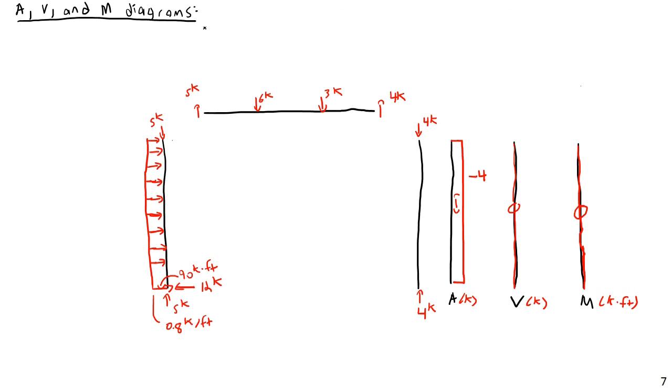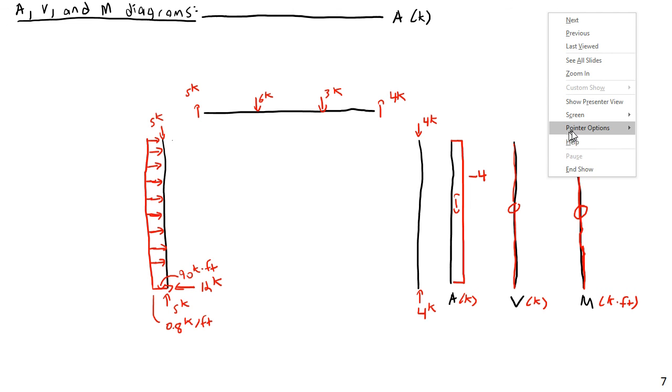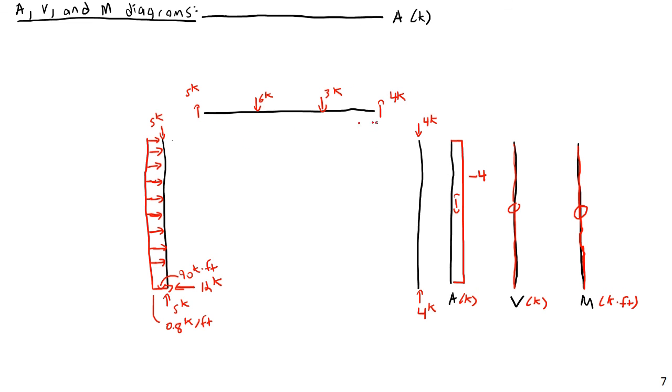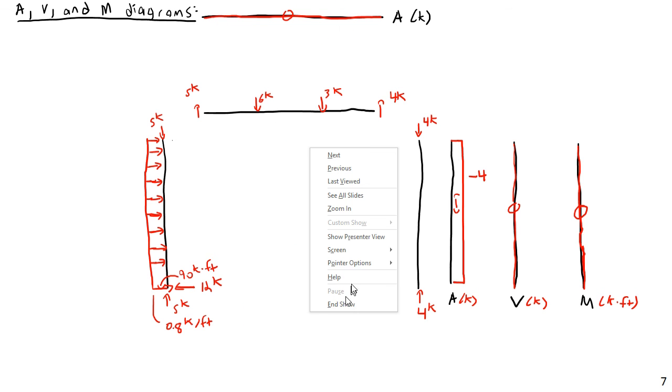First, maybe I'll get the axial force. I'll hide the axial force way up here because this is going to be kind of cramped. My axial force here is going to be 0, because on this beam there are no horizontal forces applied. And on these, I just like to put a line right along the axis, and then a 0 on the axis to indicate that, but that's definitely just a stylistic choice.